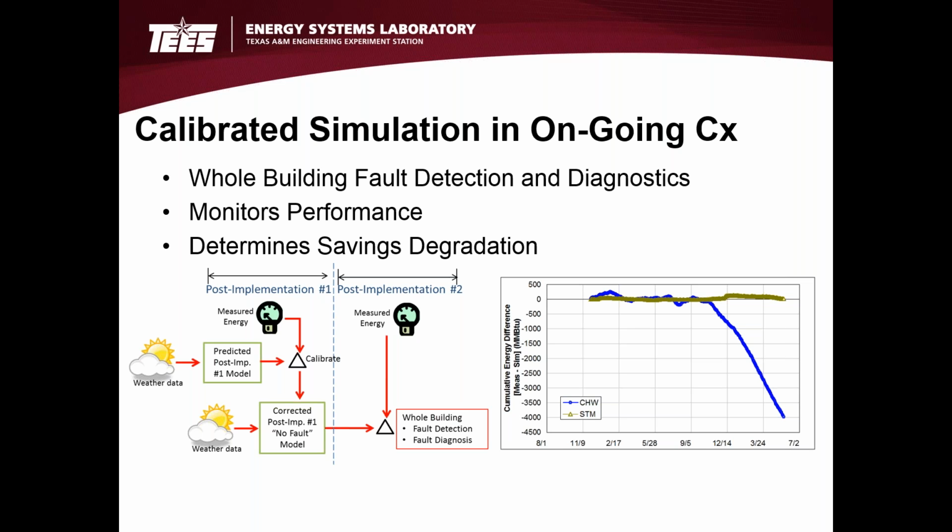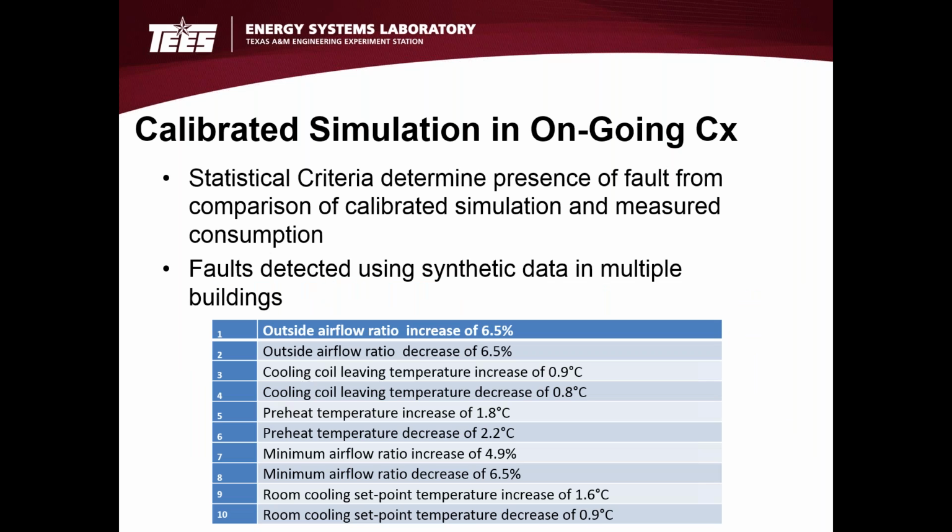And so we were seeing substantial additional cooling showing up whenever there was a high latent load. Simply cooling the air wasn't causing an issue, but when the latent loads in the outside air got higher, it was providing more latent cooling than was required, and that showed up as substantial additional cooling required in the building.